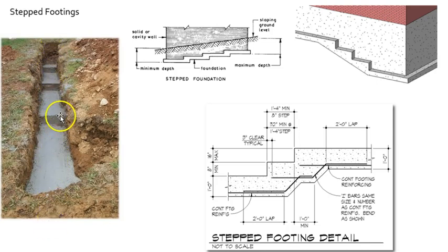So if the structural engineer specified call it a 12-inch wide footing, probably more than that, I can't really scale here, 12 or 16 inches, the earthwork contractor would get a bucket that's 12 or 16 inches wide and just dig it out, and then that footing could be poured directly into the earth because the earth is stable, as opposed to having to set up forms.